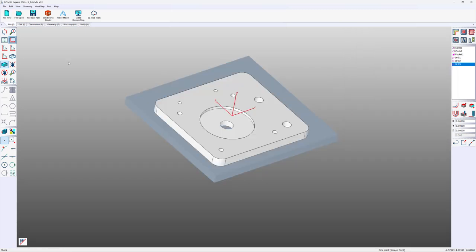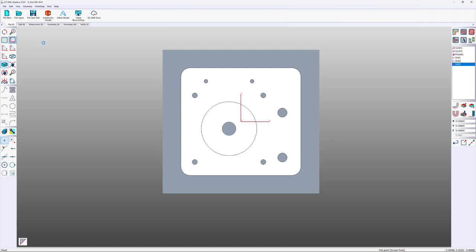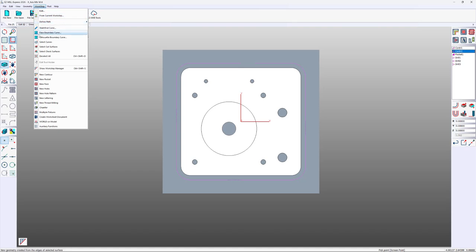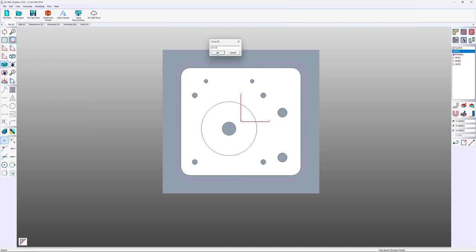Okay, now it's time to get rid of those tabs. So I have to create a boundary curve. Then I have to trim so that we machine just the tabs. I'd say we'll give it a little bit of an overlap, come in, then wrap it over to the next tab. The way I'm going to do that, it's a little bit of work. We'll go with a silhouette boundary curve. Put a window over our part, and it picks up all the edges.